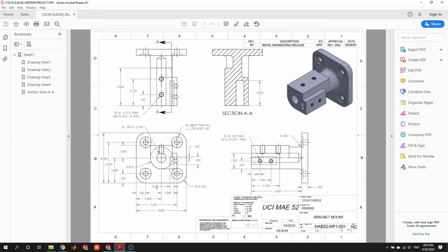But oftentimes in drawings that are in inches, you will find this. For example, this radius here at the base, it says 0.188. It's really 0.1875, which is 3/16 of an inch. So it's just something to remember, because a lot of times, if you're looking at a drawing, if you're unsure that it's in millimeters or inches, or you see a dimension and it looks a little bit strange, it could be some giveaways that either it's a fraction of an inch that is missing a decimal place, or is in fact in millimeters. Of course, this whole drawing is in inches, but just to let you know why that number may seem strange when some of the other ones are nice fractions of an inch.